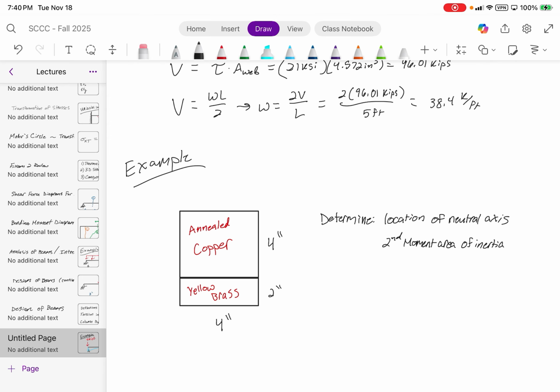And by the way, you can do these problems with more than just these materials. It's just I don't plan on doing that. Like 30 materials? Yeah, you could do them for like 10 materials. It's all the same process. Remember when we did it for axial loads, how you had 3 or 4 different components? You would just add more material to the columns and then find the modular ratio with respect to one base material. Does that make sense?